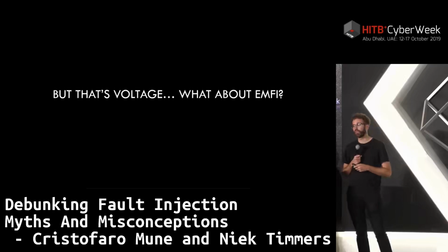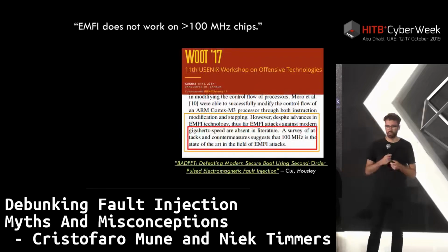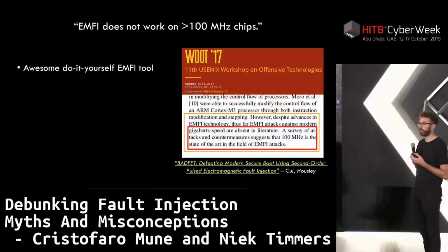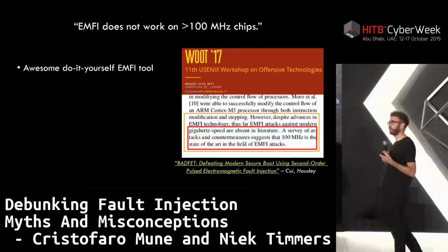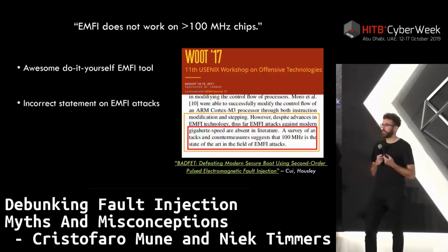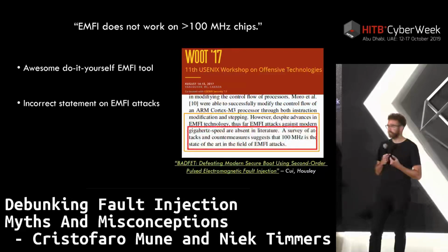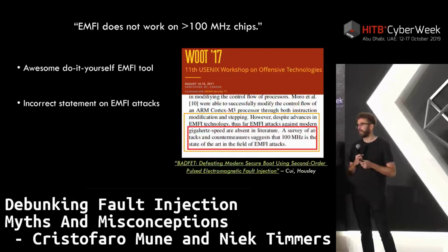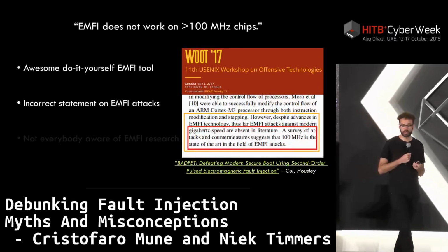But of course, this is voltage. There's a whole wide variety of other injection techniques. So what about EMFI? In 2017, a very nice paper came out where the researchers developed a do-it-yourself EMFI tool that allows you to inject an electromagnetic field into the chip in order to cause glitches that manifest themselves as faults. However, they made an incorrect statement on EMFI in this paper. This is not bashing in any way, this is just being unaware of results that were already presented earlier. Here they state that these attacks are not applicable to chips running above 100 megahertz, and that the literature actually states so.